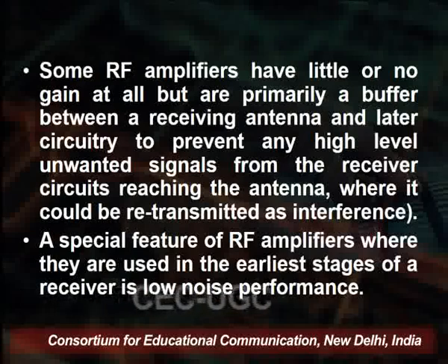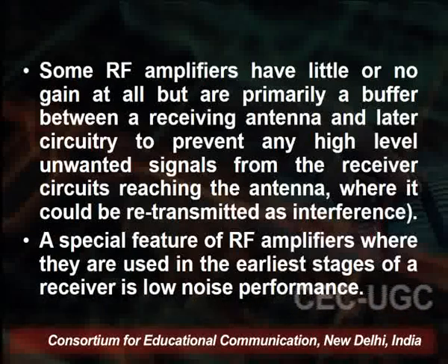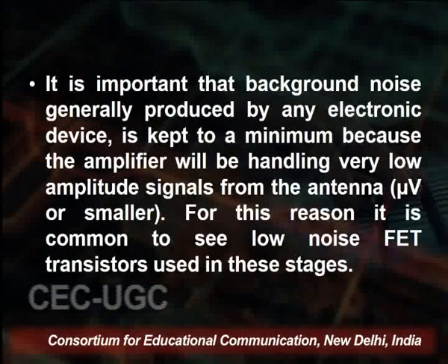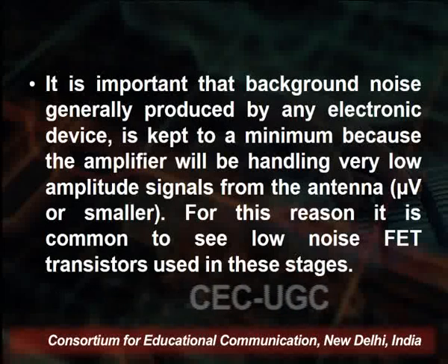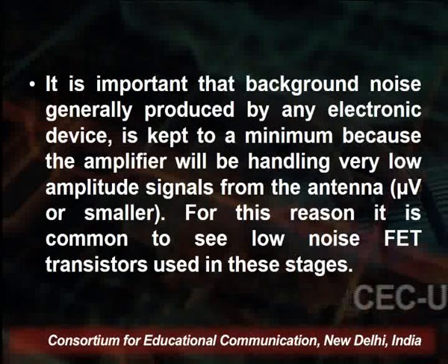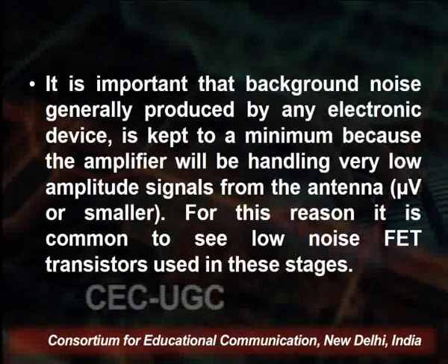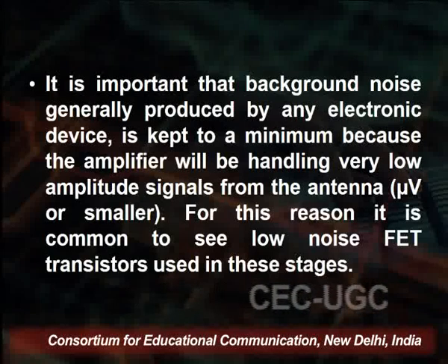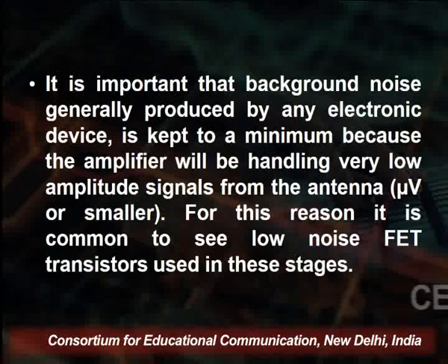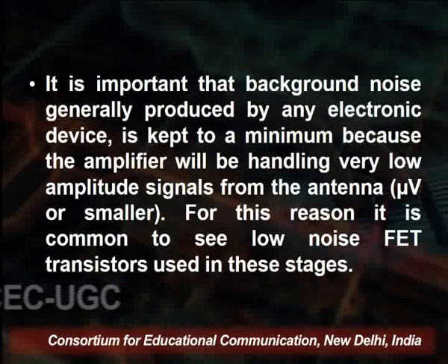A special feature of the RF amplifier, which is used in the earliest stage of the receiver, is low noise performance. In the radio frequency stage there is very low noise because FET transistors are used in these stages. It is important that the background noise generally produced by the electronic device is kept to a minimum, because the amplifier is handling a very low amplitude signal from the antenna, that will be microvolts or smaller. That's why FETs having low noise are most commonly used.